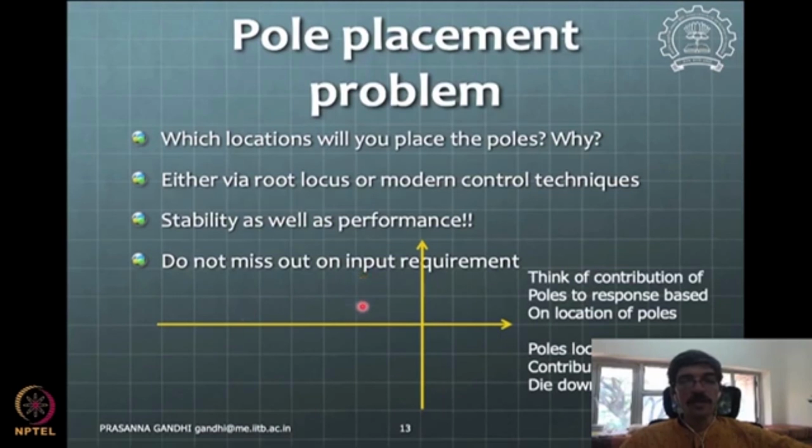So we can assume the closed loop system to have only these two poles, like a second order system, and then we can carry out some control parameter design based on the formulas that we already know for standard second order system response. Okay, which formulas are also listed here for our utility later.